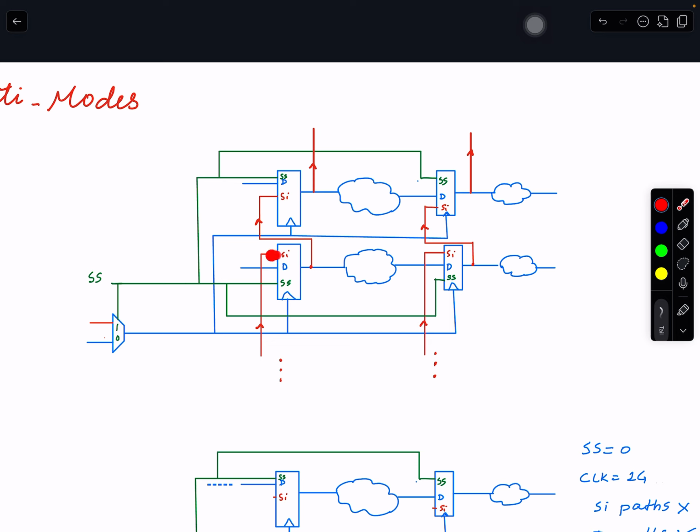Now this timing path, if you look at scan in, this comes from, let's say, another flop down here, the same type, right? The output of a flop is connected to this one. So the path that comes to the input goes a bit like this red one.